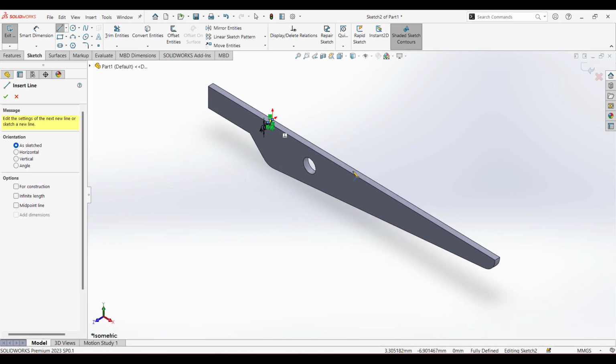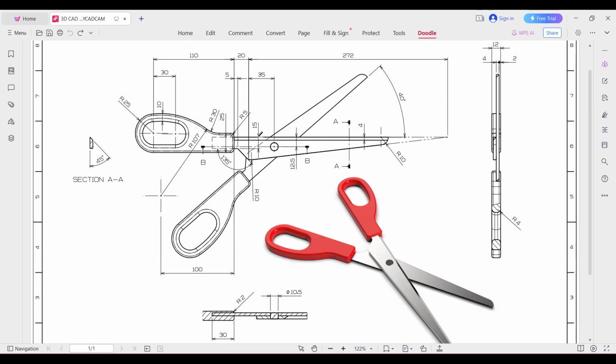Now we need to extrude cut from this portion and this other side. We can see, as our plane is the right plane here, we'll extrude both in this portion to 275 units, and this other portion is 20 units. And we don't need this inner portion to be edge cut. If you want, you can give it, or you can leave it blunt here.